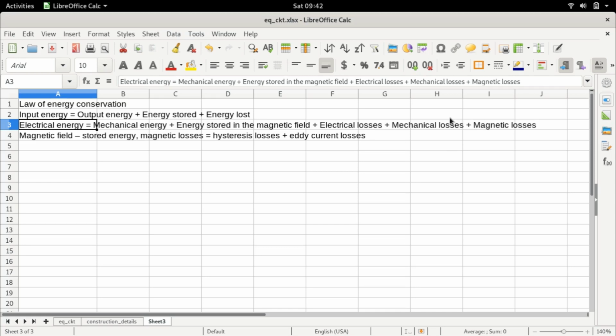the total losses. Right. Now, we can say that out of all these losses, some are significant, some are insignificant, right? For example, the magnetic losses are usually insignificant unless you have a really old motor in which the lamination has almost broken down, or some other issues have happened because of which the magnetic field is really messed up.